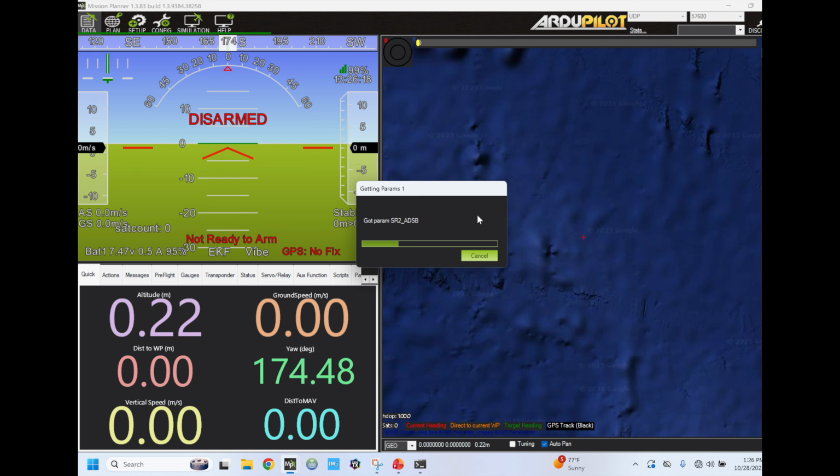Namely, the Shannon information capacity theorem says the bit rate available depends on the signal to noise. So if you have a low signal to noise, which we have for long range radios, then you have a low bit rate. If you have a high signal to noise, which we have for short range radio, you have a high bit rate. So now you will never forget that theorem until the day you die if you take my class and use ELRS for telemetry. So we have to wait because of Shannon.